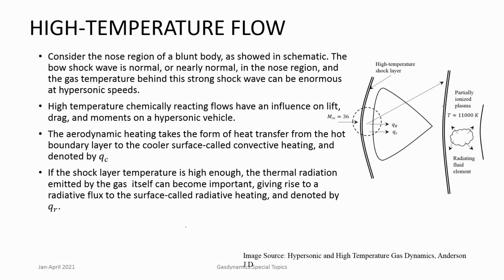Temperatures computed by considering a calorically perfect gas can be bizarre numbers like 11,000 Kelvin or 20,000 Kelvin and so on. But one has to carefully consider this, because the calorically perfect gas assumption no longer holds good.